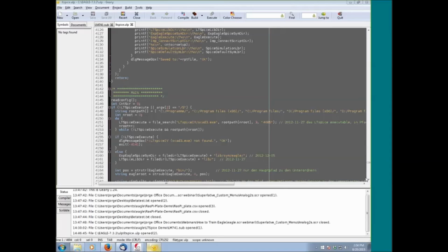Excellent question. What about the possibility of IBIS simulations? Awesome. In the case of LTSpice, LTSpice is strictly an analog simulator. It doesn't handle the signal integrity stuff easily. It cannot handle an IBIS model. You can do some signal integrity by simulating transmission lines and such, but the program we're going to analyze next month, PCB Sim, can do full-blown IBIS simulations.